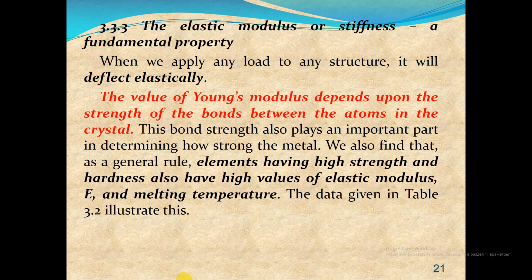In this case, the deflection will be too small to measure with any extensometer or normal strain measurement device, but deflection will occur nevertheless. Finally, note that with elastic deformation, the atoms stay in the same relative positions to each other. So no atom shifts its position relative to its neighbors.